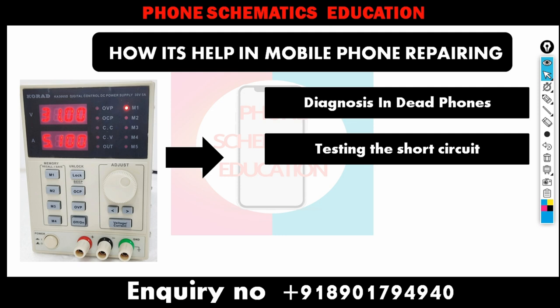If the current consumption is high, then we call it a full short. According to the current consumption, we can decide what type of fault it is. Also, when you press the power on/off switch and there is no consumption, the fault is in a secondary line, the eMMC, or the CPU does not respond. So you can get an idea through the ampere sequence. I will share the whole sequence in this video.